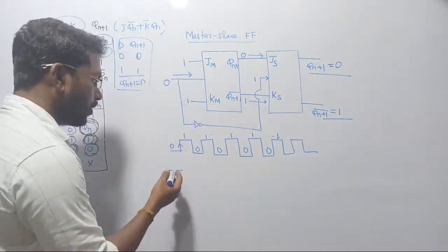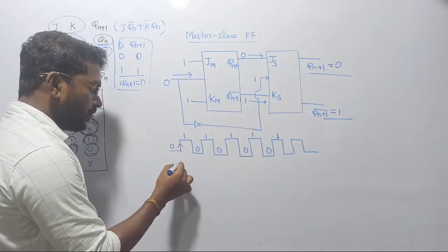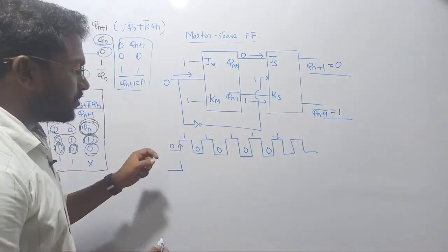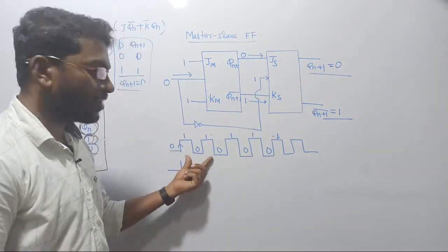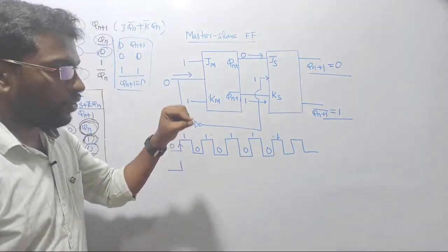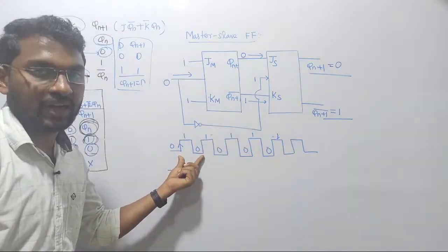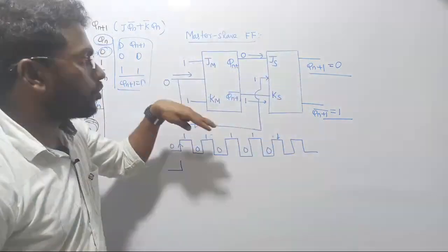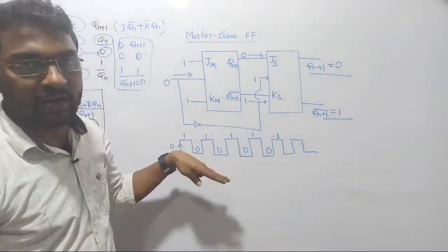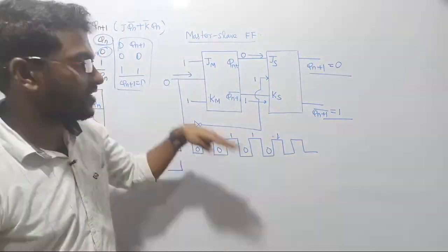So anyway, let us assume in order to overcome this issue we have to set... The reason this race around condition happens is that in your circuit, at the input side, in your flip-flop your data keeps on changing. Right? Feedback data comes back, and the system output keeps changing. Input data changes, and the output changes immediately.